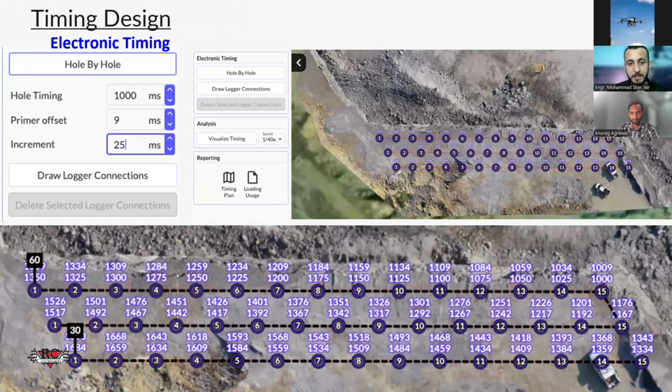So, yeah, I think I can answer this question. If you are planning on Google Earth, just mark the line which you want, mark the waypoints like a line. So every point you make on Google Earth will be a waypoint on the controller. It will be fixed coordinates.